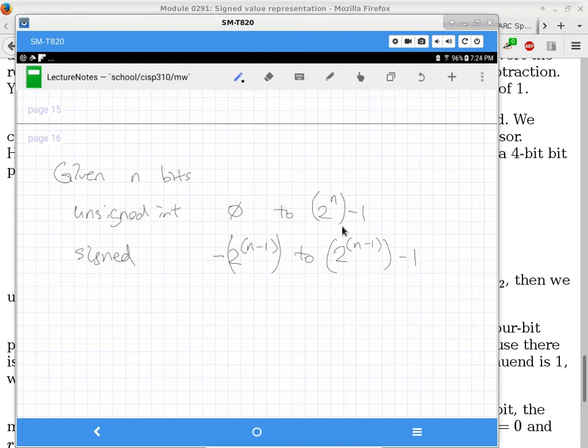And then many of my students encountered a problem. It worked just fine on the PC, but it doesn't work all the time when it is actually on the robot. It works when the displacement is relatively small, but when you try to specify a bigger displacement or a higher speed, it stops working. Everybody was scratching their head. And then I asked, so how wide is an integer for the AVR platform? Because that's AVR GCC, which is a cross compiler for a different processor.